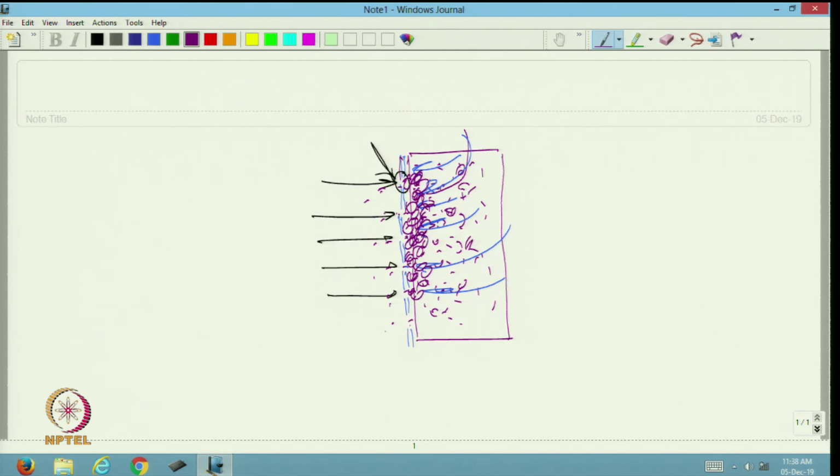After formation of this cake-like porous structure of particles, the geotextile will act along with this porous structure as a filter, and it will allow the water to flow through. This total structure will be developed with time.